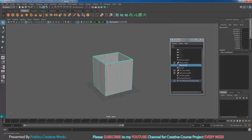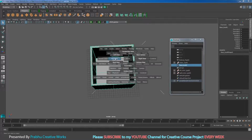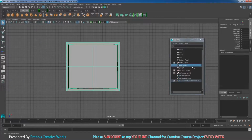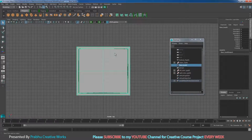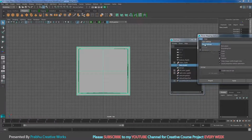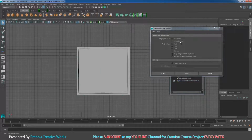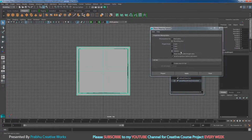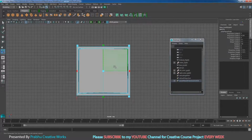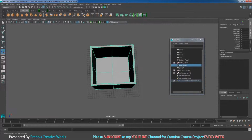I will go very slowly, so listen carefully. Now I want to go to top view. When the box base is selected with isolate select, go to UV and choose the planar option box. I will reset my settings: go to Edit and Reset Settings. Here choose bounding box and choose camera projection, which means it takes the top view as our camera. Choose keep image width and height ratio and choose project when object selected. Then right click and choose object mode and go to perspective view.